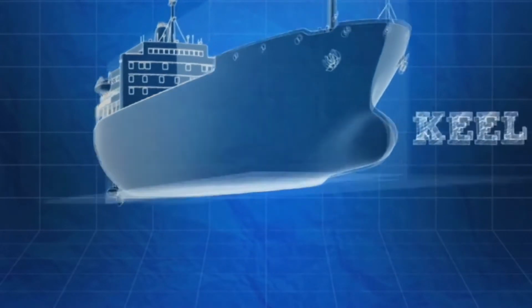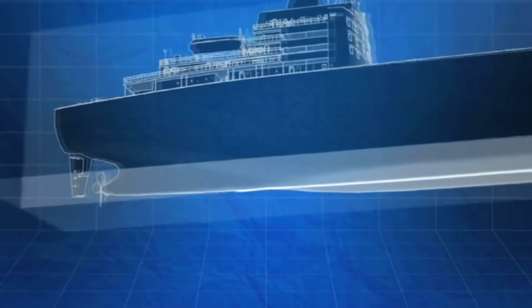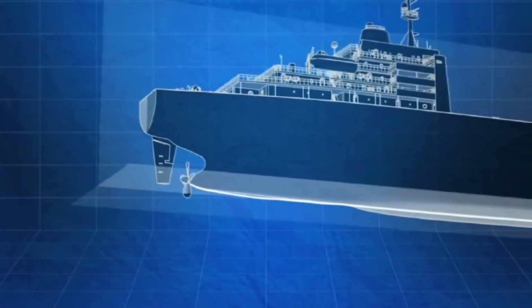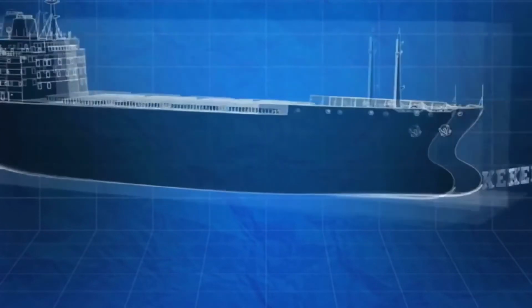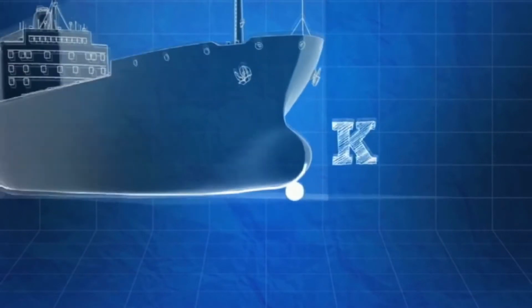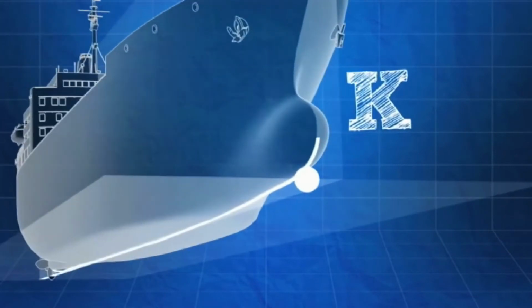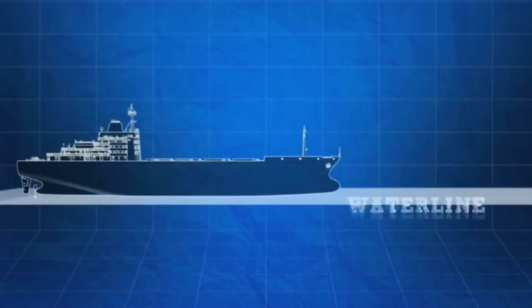The keel is the principal structural member of a ship, running lengthwise along the center line from bow to stern, to which the ship's frames are attached. The lowest point of the keel, or K, is the point from which vertical distances are measured on a ship. K is located at the intersection of the center line and the baseline.